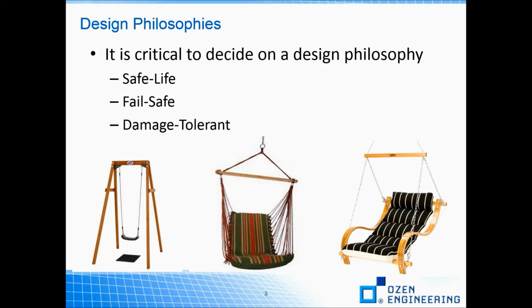The estimated life can either be calculated or obtained via testing. Then the design life is set as a fraction of this estimated life. It is really common to use 1/5 of the calculated design life for safety critical components.